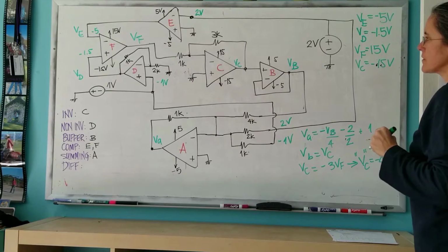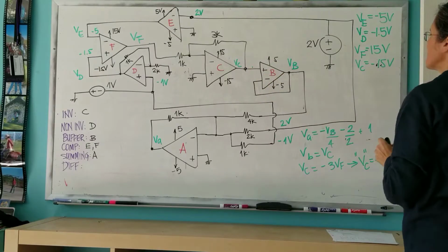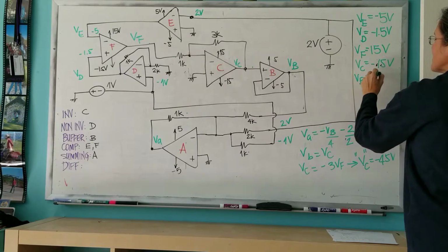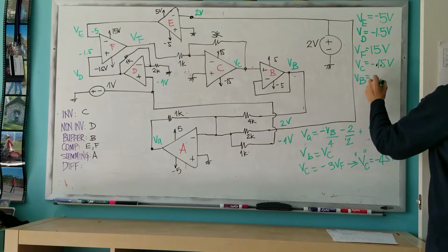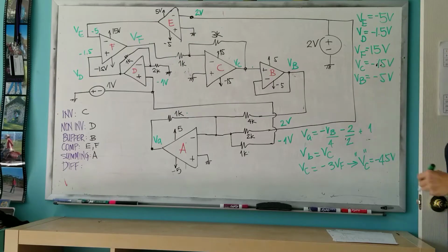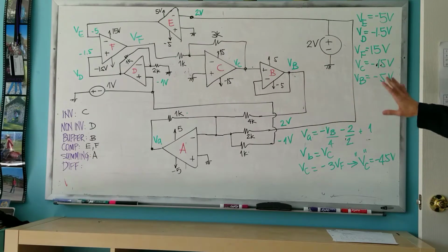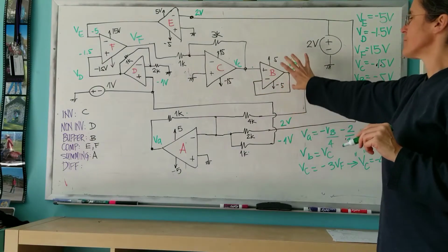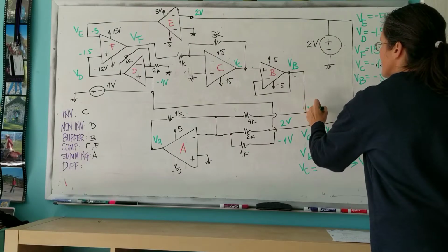We're considering ideal op-amps. And once I supply here with minus 15, the VB, even though it should have been the same as VC, is only powered by plus minus 5. Therefore, it only goes to minus 5 volts. Again, this is a paper circuit to show that you understand the limits on rails, even for a buffer amplifier. So I know now VB is minus 5.